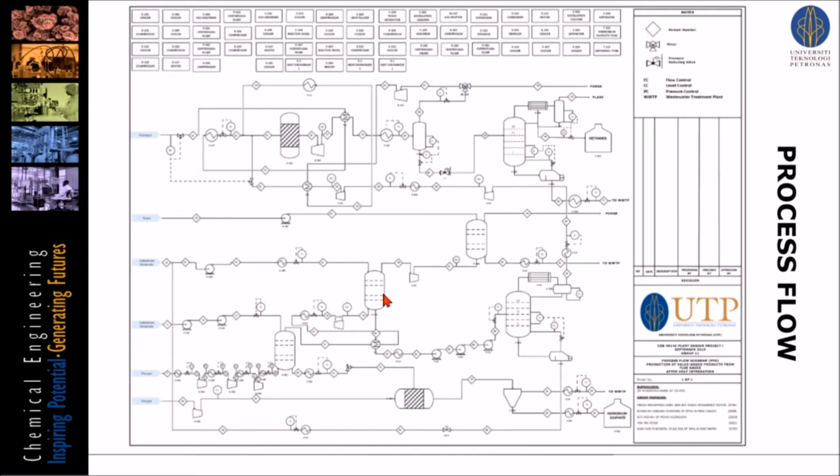Now, the liquid stream that leaves the CO2 absorber will be ammonium hydroxide solvent that is rich in CO2. It will enter a stripping unit that operates at 91 degrees Celsius and 2790 kilopascal at a conversion of 60%. The ammonium hydroxide solvent will be regenerated and recycled back for the absorption process, whereas the pure CO2 will enter the methanol reactor. At this reactor, carbon dioxide will enter at 210 degrees Celsius and a pressure of 7,900 kilopascal to form methanol and water.